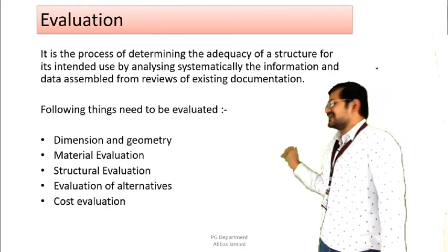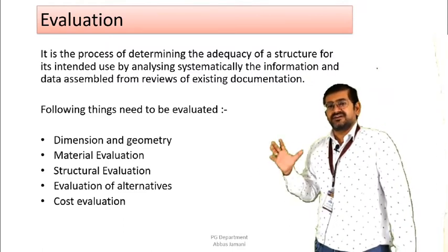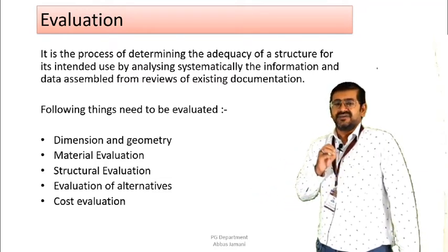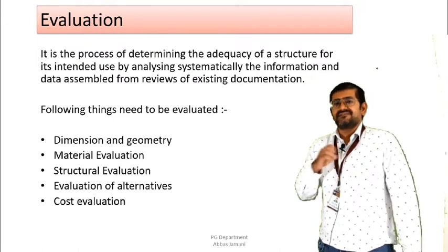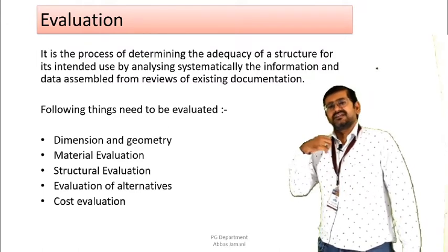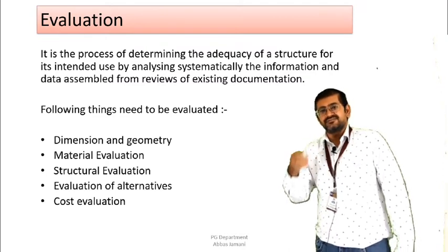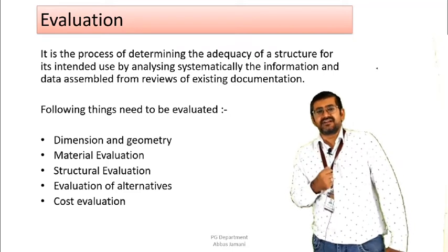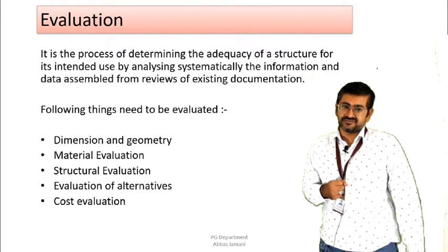Second, you do the material evaluation. That is, whatever the material test or the material data that is available with you, is it the same type of material being observed on the site or not? If any modification is there, if retrofitting material is going to be used, then what is the feasibility of using that material with the existing material? What are the properties of repair material that will be required? All these things need to be studied under the category of material and geometry.